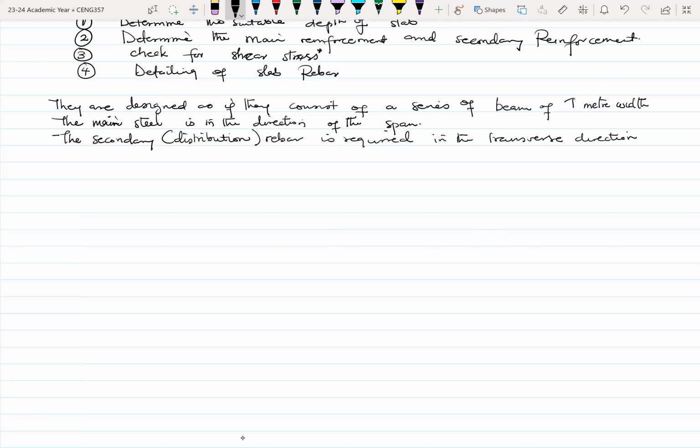And normally when you're positioning, the main rebar is always the most bottom or the most top rebar. For example, if this is a cross section of the slab, you have your supports, which could be beams, walls, or columns, whatever they are. Let me increase the thickness of this here, just for exaggeration purposes.